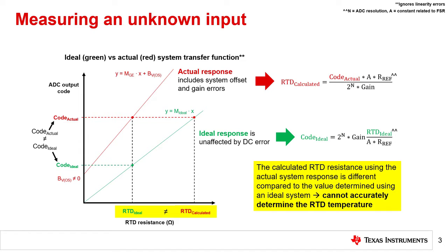Calibration is therefore necessary to understand the behavior of the actual response so we can accurately determine the RTD temperature from the measured resistance. The next slide discusses which errors can be removed by calibration.